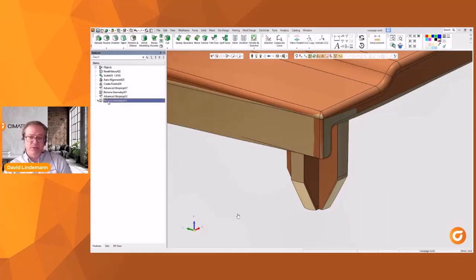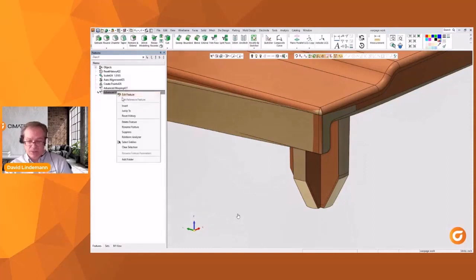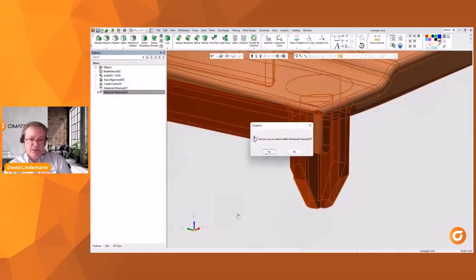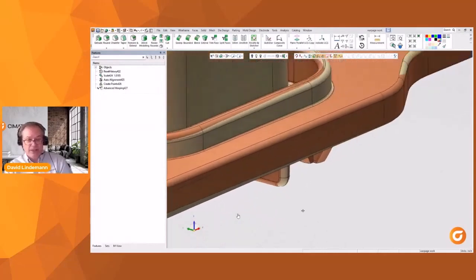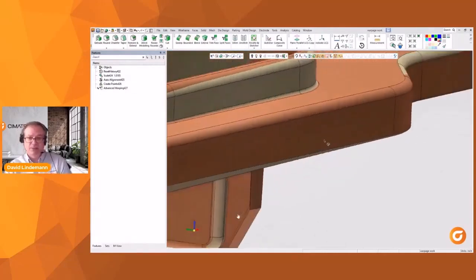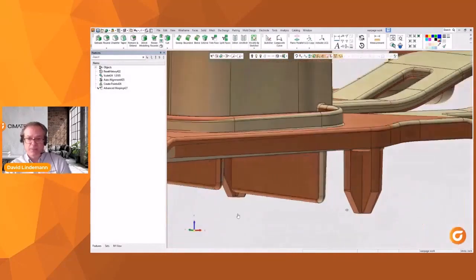So if you have a simple change, it's pretty straightforward to just snap a part out like that, and you'll see it bow. Like maybe the part on the one side bows in, so you have to compensate. Say it bows in 1.5 millimeters, you have to compensate by bowing it out 1.5 millimeters. That is very possible with just this one click, this one function.